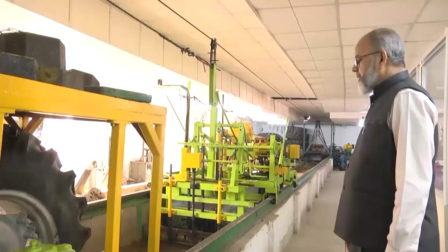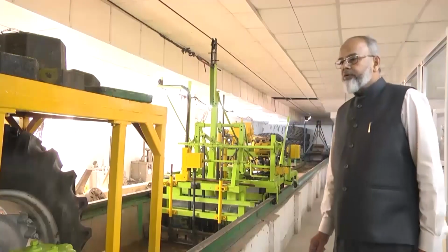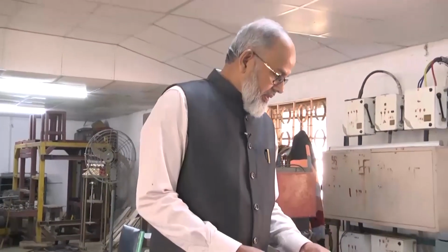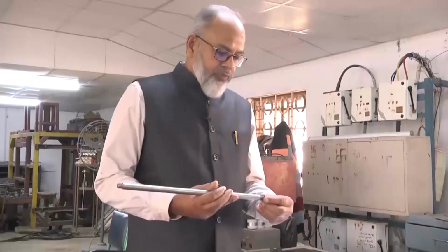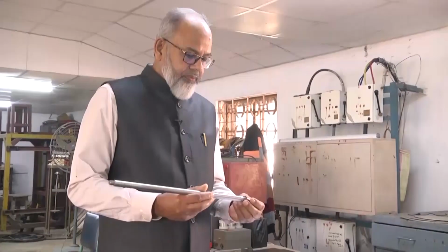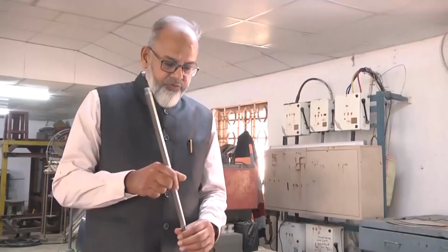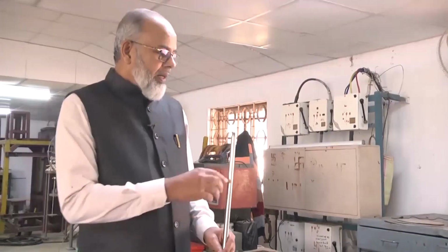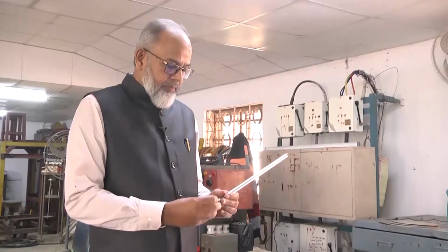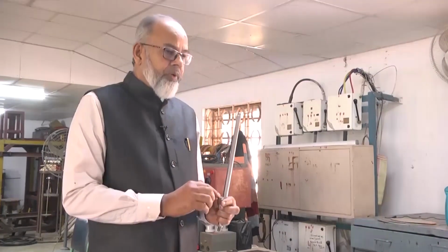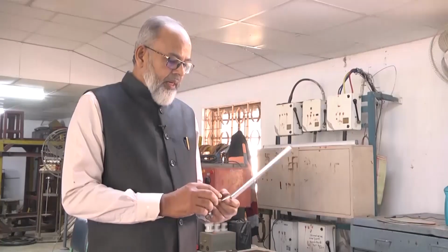explain how to measure the strength of soil using a static cone penetrometer. This is a cone penetrometer, where the cone has been removed from the shaft to which it will be attached. This cone along with this shaft has to be pushed into the soil of the soil bin, and how much force you are applying has to be recorded. The base area of this cone is 3.23 square centimeter, and the angle of the cone is 30 degree.